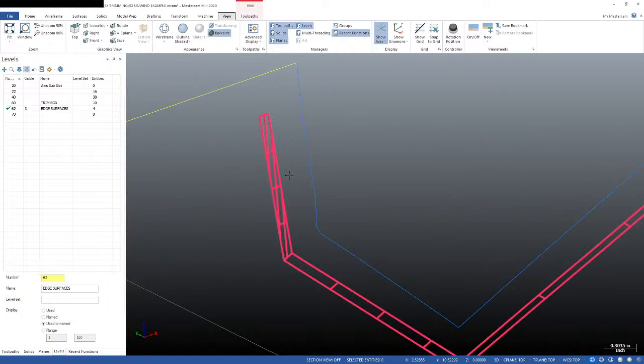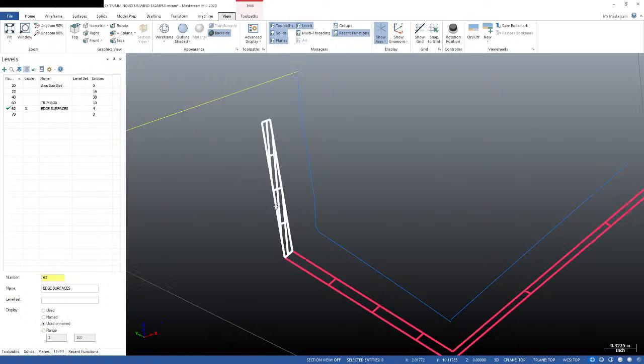That means that depending on which tool we use, we have to be careful about the quality of our surface itself. Sometimes we have to end up rebuilding a surface by either using ruled or net or some different method so that we can create a surface where the UV directions are favorable for machining.